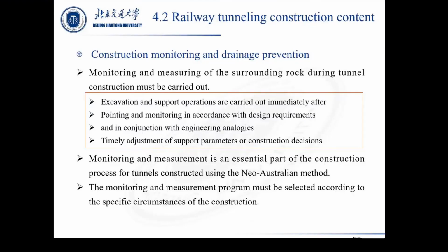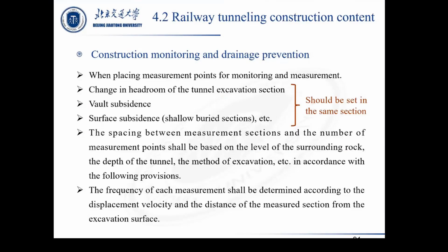The monitoring and measurement program must be selected according to specific circumstances of the construction and other matters, should be set in the same section, and the space between measurement sections and the number of measurement points should be based on surrounding rock level, tunnel type, and excavation method.